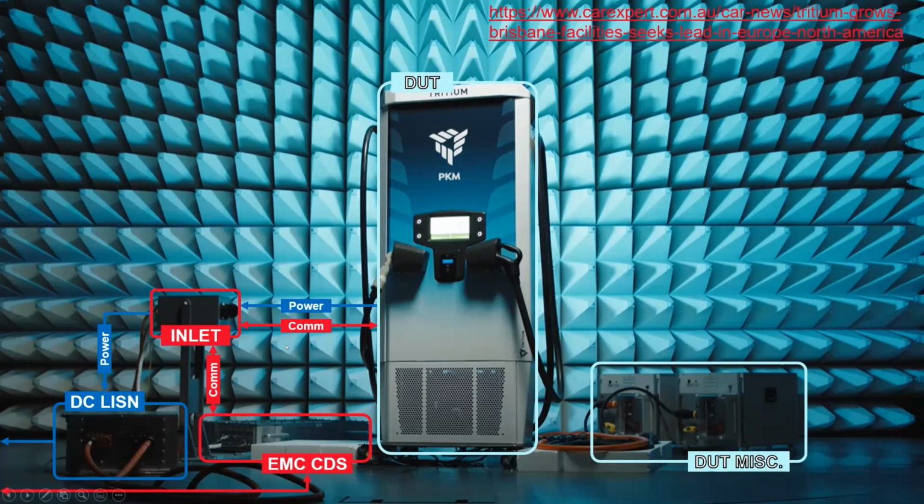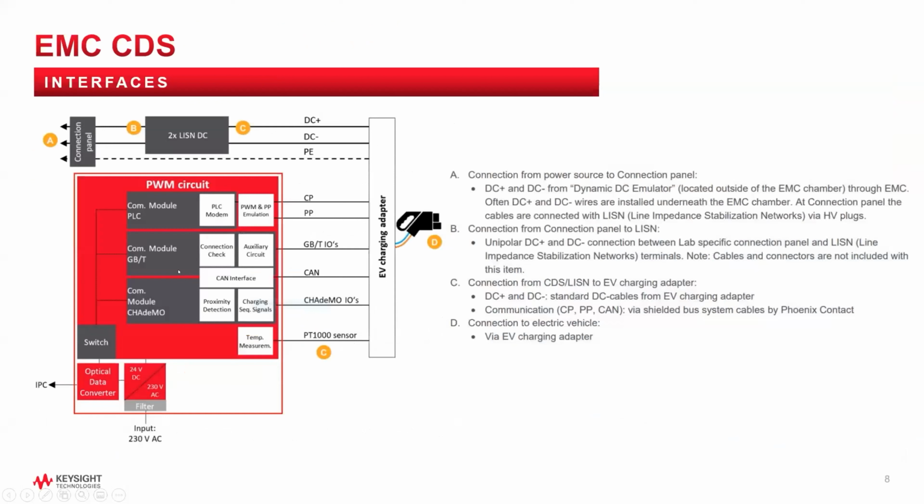A better understanding of this would be this particular slide here, where we go into the quick show of the general concept of how we can connect and implement our system in an EMC chamber, whether we're testing a subsystem, an EV, charging station, it doesn't matter. The first interface, of course, here is the connection panel up here, A, where our DC power enters the chamber via high voltage plugs mounted to the panel. Now, this connection panel would be lab specific and tailored specific to the needs of the test and in the lab.